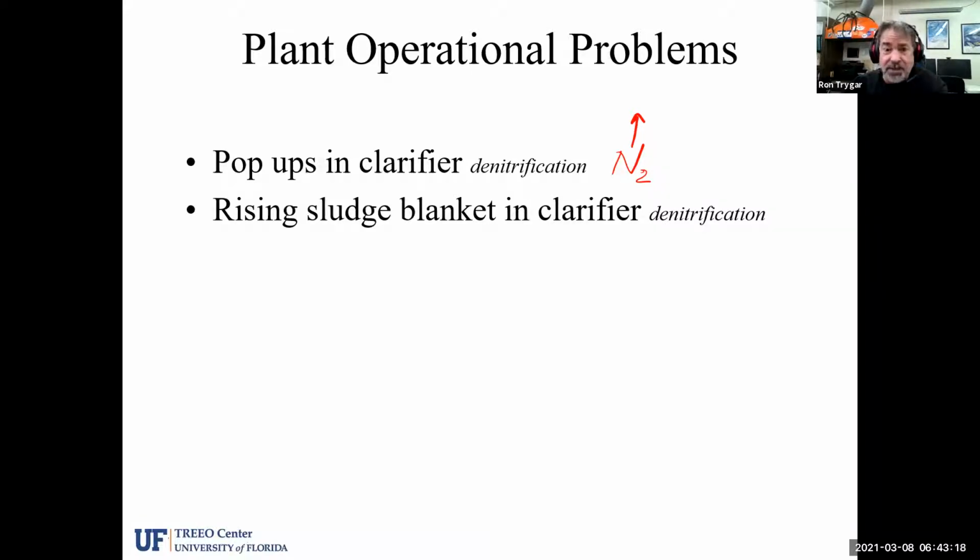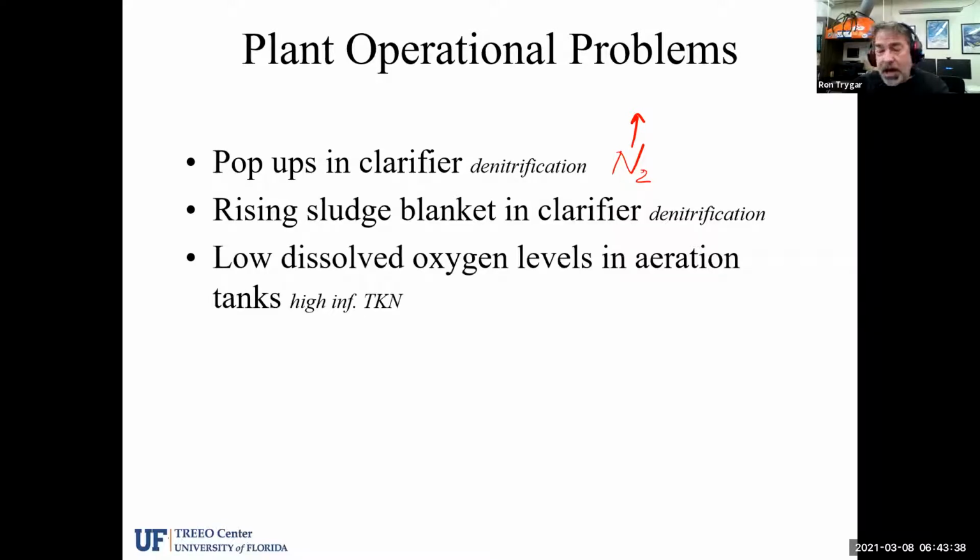Sometimes your actual settleometer rises within a few hours, and you wonder why that happened. So we want to take a few minutes to talk about that as we go through this class. Again, nitrogen gas rising to the surface can cause rising sludge blankets in clarifiers and pop-ups. We know that high amounts of ammonia and organic nitrogen that enter treatment plants can cause an oxygen demand on the actual bacteria, or the oxygen we're supplying to the bacteria.